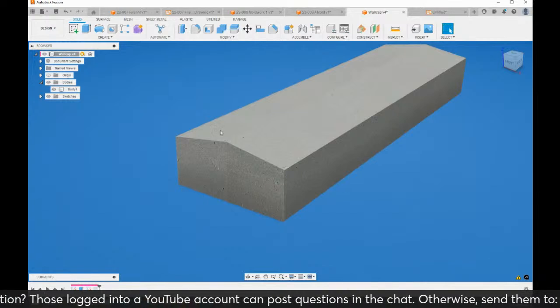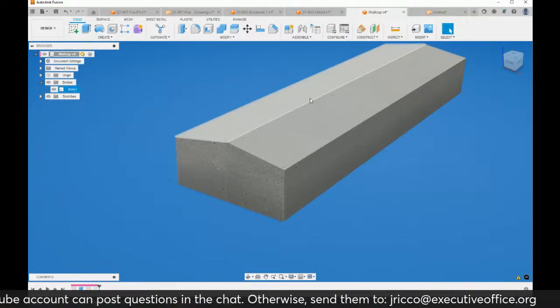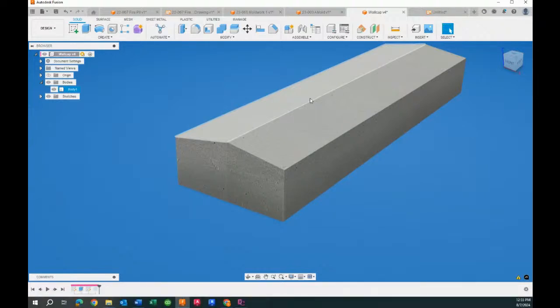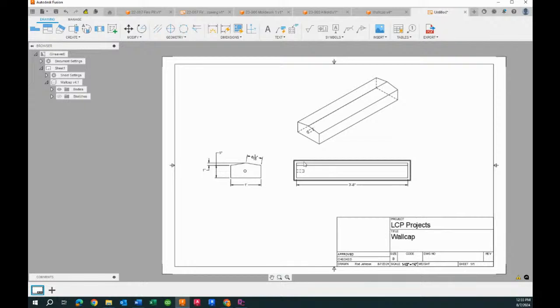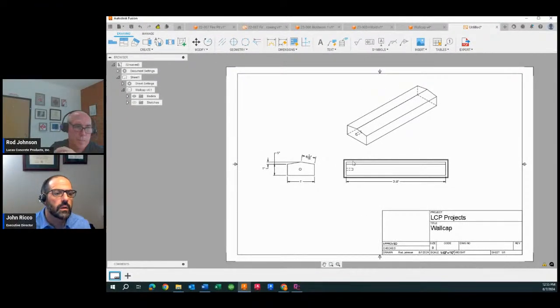What's good about something like this is you can build your models. And that's the whole parametric element of it. Especially for the handset world, they could take these things, and conversely, you could do the same thing for your form work. Once you've created it and defined your parameters, it takes a little bit of time to do that. But once you've done that, you can turn on and off those features within the timeline, and then go back to the drawing file and get it to spit out what you want it to spit out. That's one big, huge time saver in terms of ticketing. And then the second thing is if you have parts that you want to cut out, whether it's on the CNC or directly onto a foam cutter, for example, you can do the same approach with the parametric software. So.